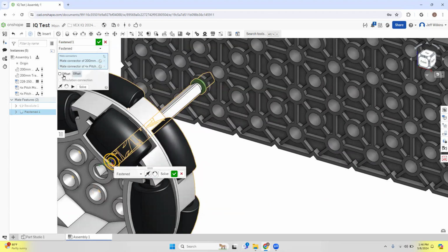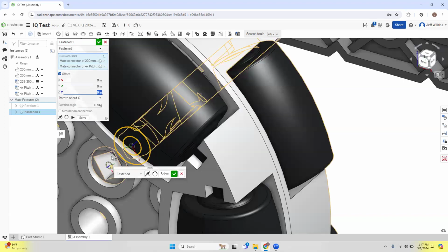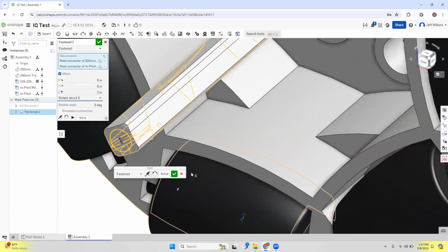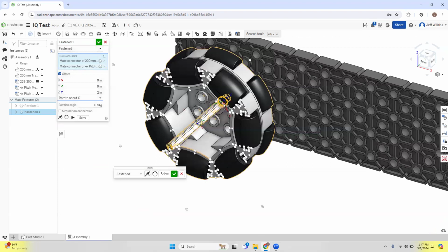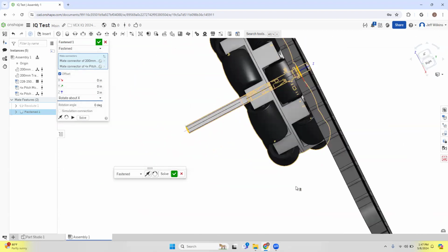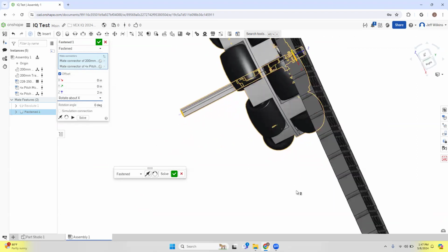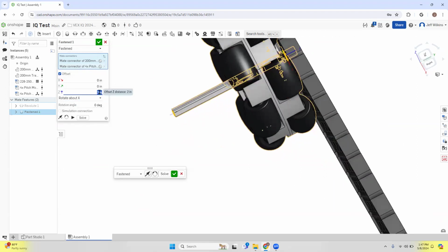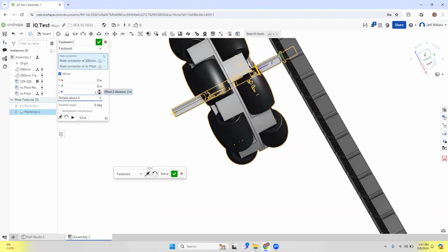And then you can use the offset tool and you can push it back and forth. So in this case, if I look at the origin, way down in here, you can see that blue Z. Usually the Z axis is your one, and I'm going to just say 2, hit tab, and now you can see it pushed it 2 inches into the material. I'm right clicking and I can spin this around. You can see that's too far. So I'm going to make this 1.5, tab.